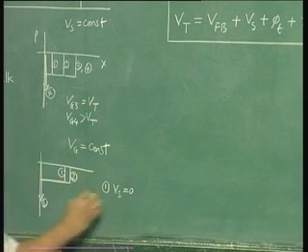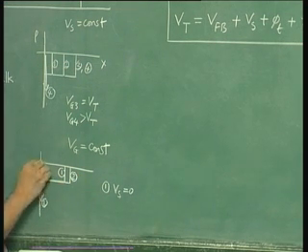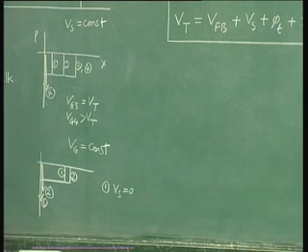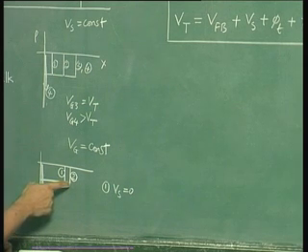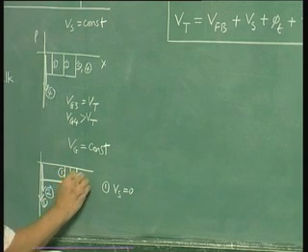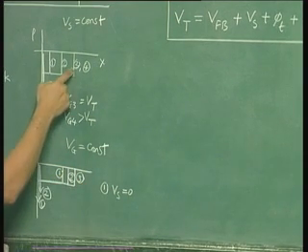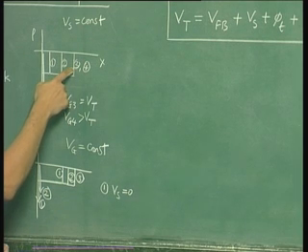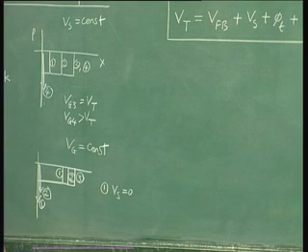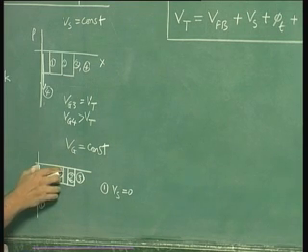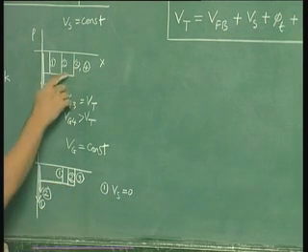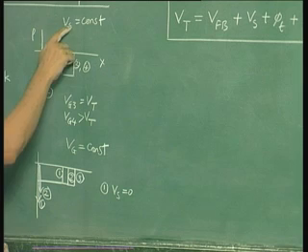So this is 2, and inversion charge is decreasing simultaneously. And for 3, which corresponds to threshold, you reach the same depletion layer here that you had, assuming that this Vs is the same as the Vs corresponding to this. So you started with a smaller depletion layer thickness than this, because 1 corresponds to Vs equal to 0, whereas this threshold condition corresponds to some value of Vs.